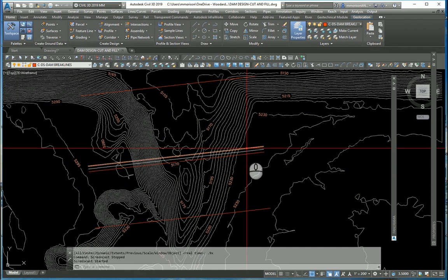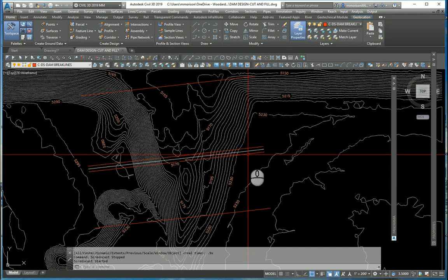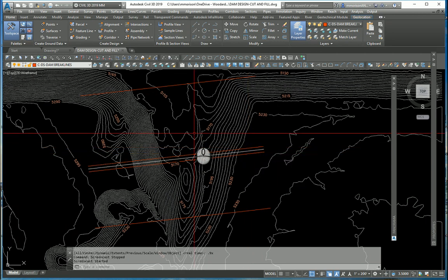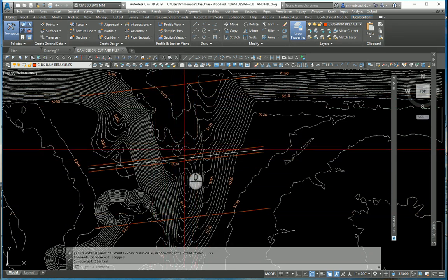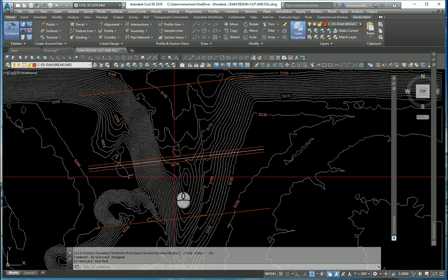So what I've done is I've created the crest of the dam 20 foot wide. I brought these up to elevation 5225, an elevation on those two polylines. His criteria for the dam is a 3-to-1 slope this way and a 2-to-1 slope this way. So I did a stepped offset of around 100 feet out here, because that'll be big enough to build a dam in here.